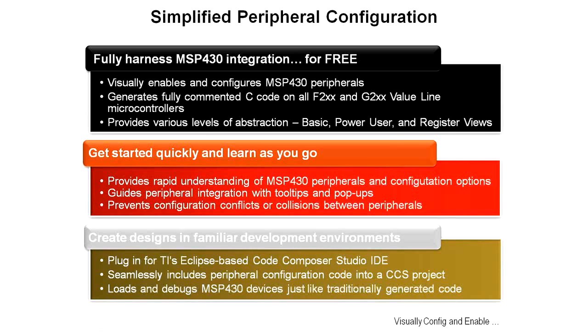The intent of Grace is to simplify the peripheral configuration, to allow you to fully harness the MSP430 integration for free, to visually enable and configure the MSP430 peripherals. It will generate fully commented C code on all F2XX and G2XX value line microcontrollers. Fully commented, human readable code, not some kind of strange stuff that you can't understand.